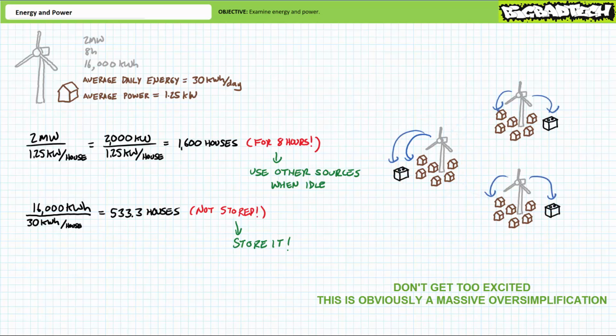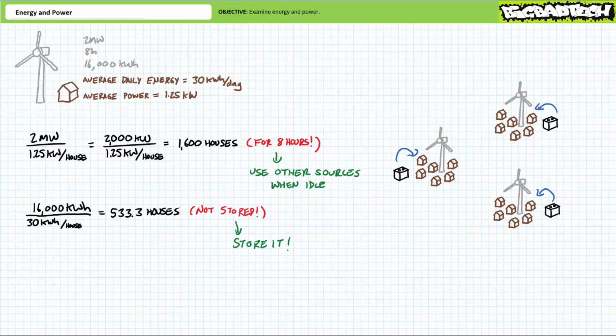Add to this transmission scheme localized battery storage in regions A, B, and C. When it's windy in 2 or more regions, any excess power is stored in these battery banks to account for the inevitable day when the wind refuses to blow in any of these regions. Keep in mind, energy storage needn't be limited to electrochemical means as in batteries, but can also take the form of pumped hydro storage, where in the event of excess power production, water is pumped uphill, and in the event of need, it's allowed to run downhill and turn a hydroelectric turbine.